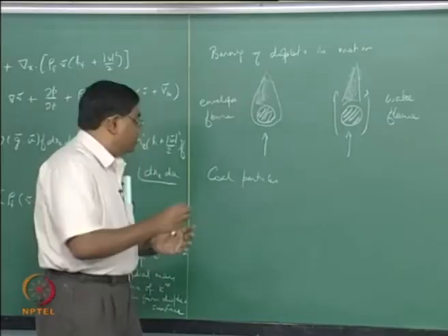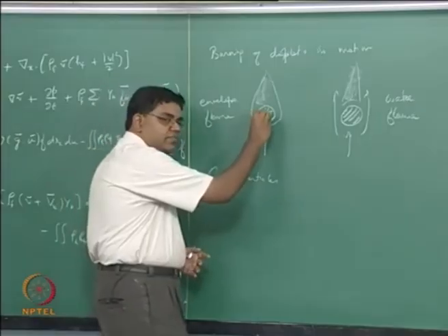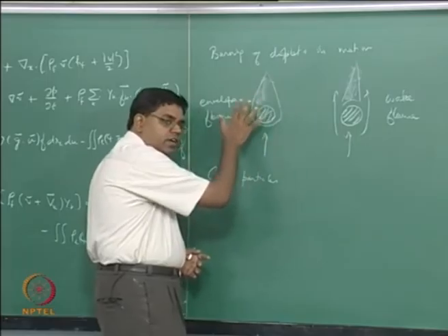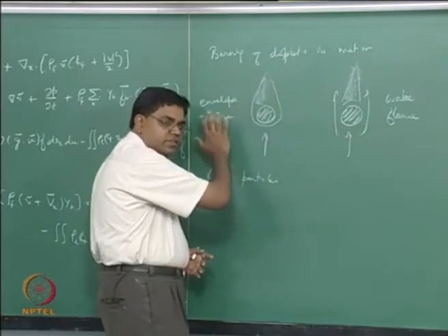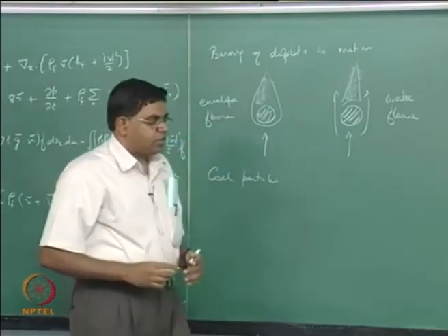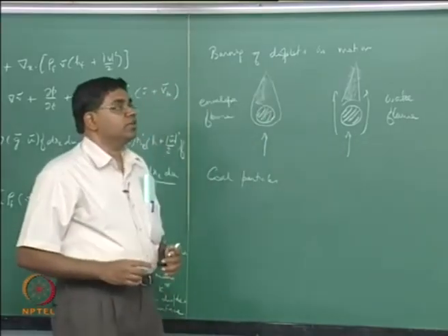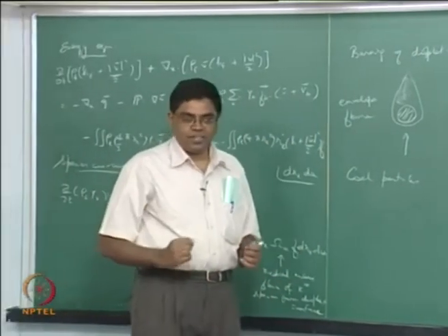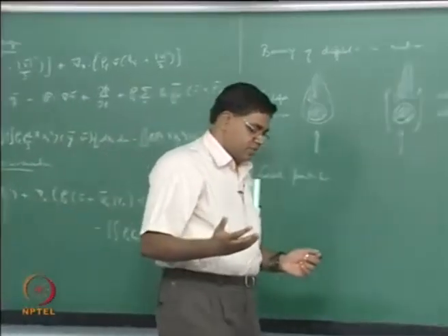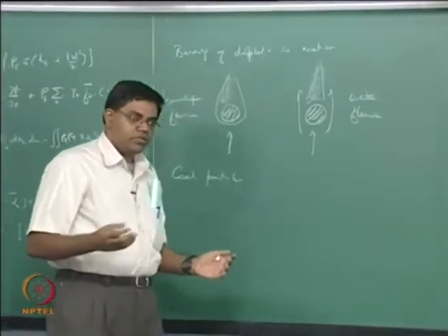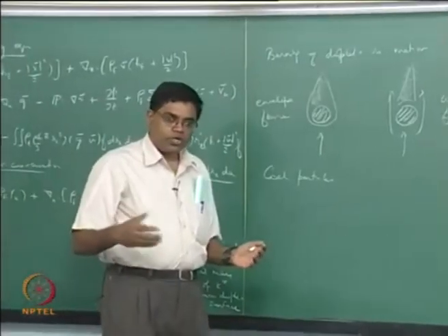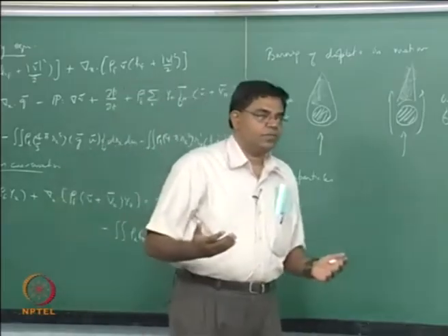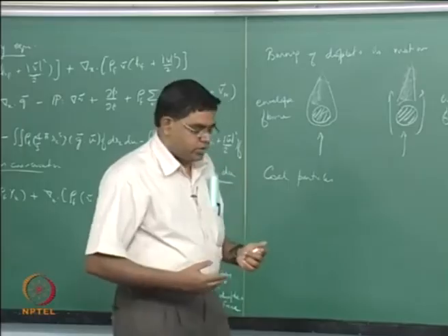and you could get into volatiles that are volatilizing from somewhere near the core, through the less volatile substance, penetrating through that and then coming out as gas, right. One of the dramatic examples for that is, for example, something called aluminized gelled kerosene. Kerosene itself is a multi-component fuel. On top of it, let's say you try to gel it with aluminum, and aluminum is obviously less volatile when compared to kerosene.